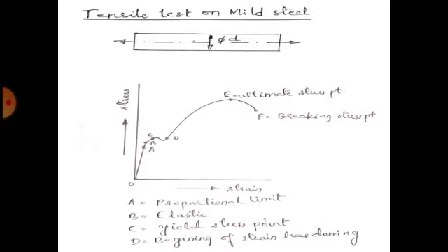Now consider a bar of diameter D which is acted upon by a tensile load. We have studied in chapter of simple stresses and strains that whenever some external system of forces acts on a body, it undergoes some deformation. If a body is stressed within elastic limit, the deformation entirely disappears as soon as the forces are removed. It has been also found that beyond the elastic limit, the deformation does not disappear entirely even when the forces are removed, and there remains some residual deformation.